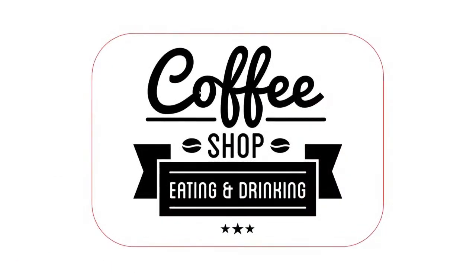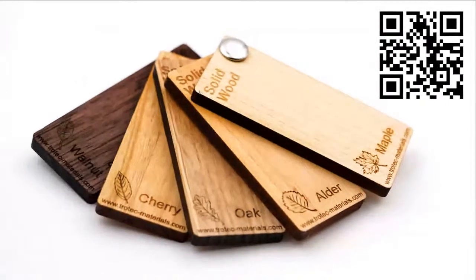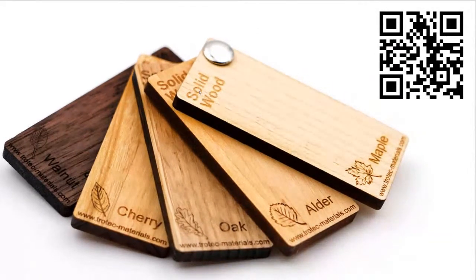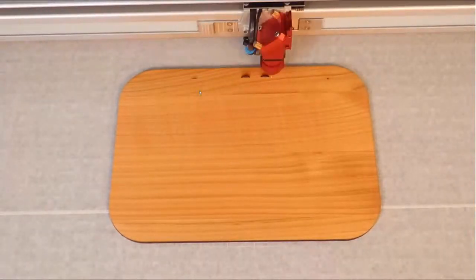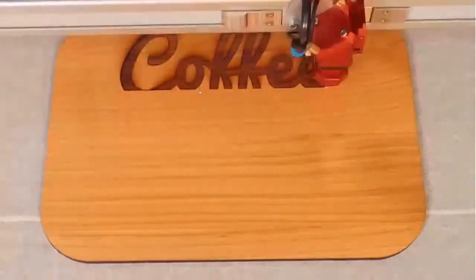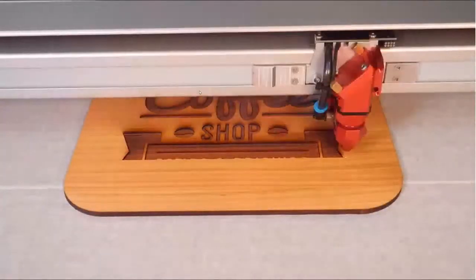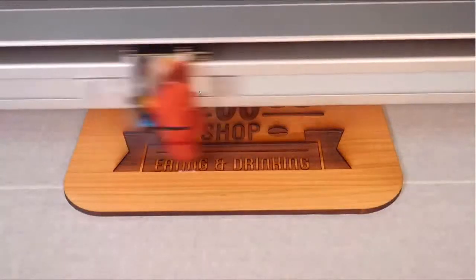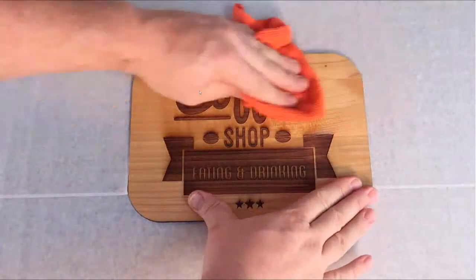And here's an example. Here's a simple coffee shop type sign that's already been cut out. I'm going to engrave it here on solid cherry wood. I do prefer lighter grain woods, because when you engrave into wood, it's going to produce a dark effect. And so if you're engraving into a dark wood, then you're going to see a dark effect on dark wood, and the contrast is going to be lower. So lighter wood species are going to work better. Also, tight grain woods like cherry and maple work much better than, say, oak or pine because of the grain. You really see the grain on some types of wood. So type of wood can make a difference.